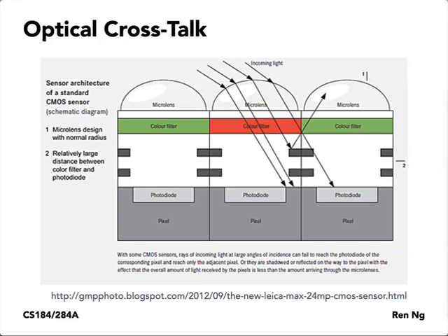So that light, some of the light at least, is arriving at a large angle compared to the optical axis here. It may go through the microlens and get bent, but some of these rays may get bent and still hit the metal parts, get reflected off, and be lost. Others, this is the more problematic one over here, may bend, but actually go through the color filter array that's here, red, but go over the top of this metal stack and end up in the next photodiode. This is called optical crosstalk of the color information.